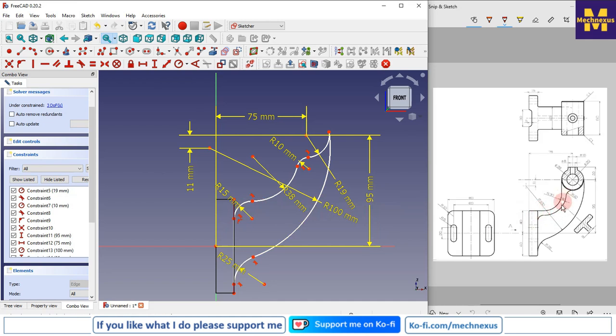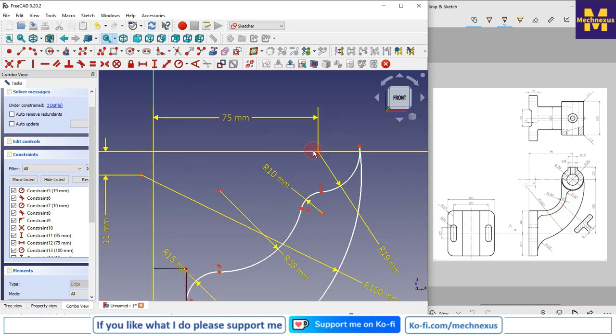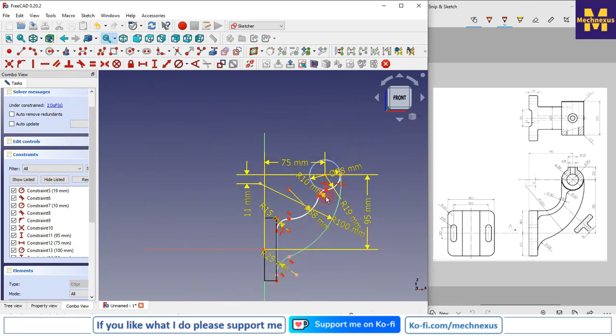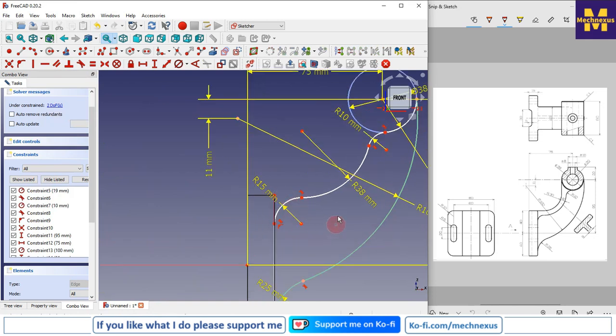8 mm wall thickness. Okay, so for this we need a construction circle. So without this we would not be able to fix this. So we will draw a circle and make it construction, and its diameter is 38. And this would be horizontal. Okay, so this is the constraint. Now this would be the 8 mm wall thickness.